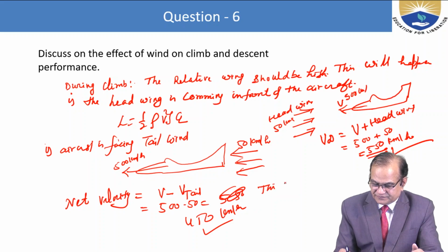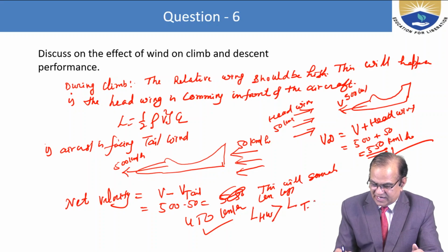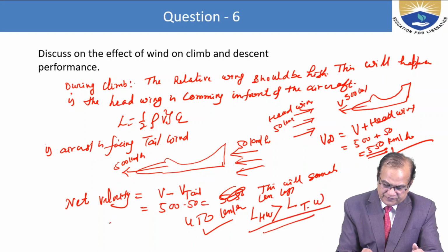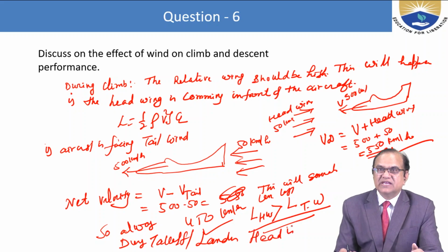This will generate less lift. So lift at headwind is greater than lift at tailwind. So always during takeoff and landing, headwind is preferred.